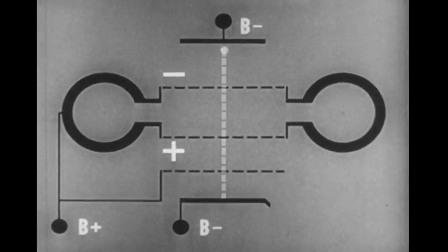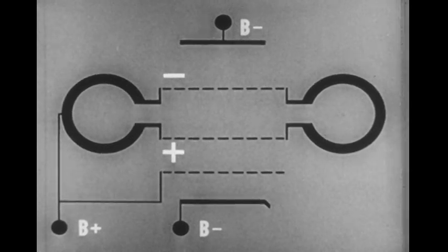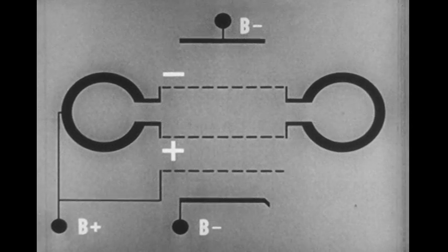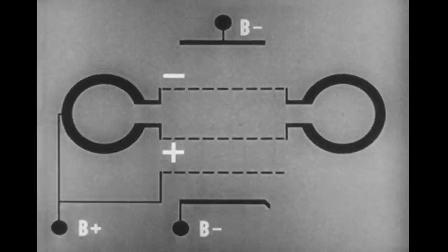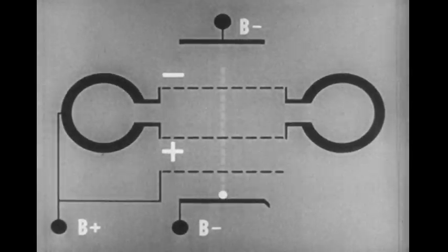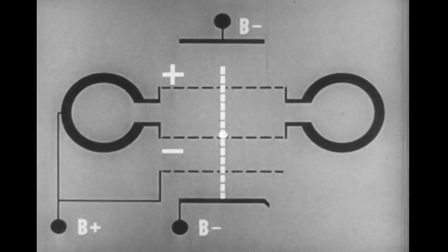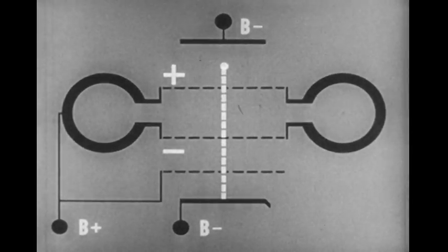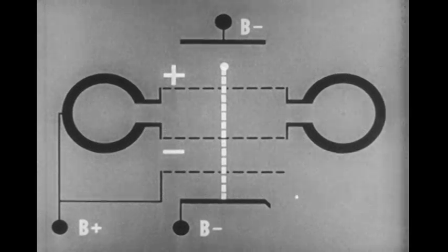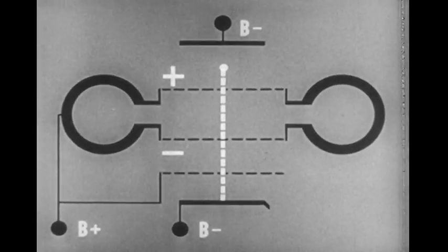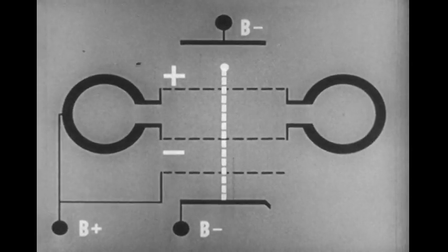The electrons passing upward when the RF field between the grids is in a positive direction will be accelerated. Hence, they will move almost to the repeller before being turned back. Electrons passing through when the RF field is in a negative direction will be decelerated, so they will go on only a short distance toward the repeller. The point at which an electron is turned back depends on its own velocity as it leaves the buncher grids and the voltage on the repeller.